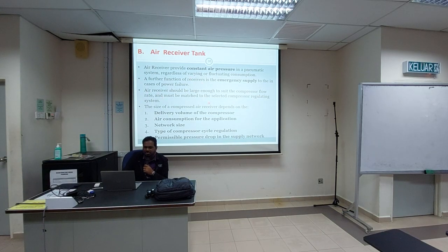Then the air receiver should be large enough to suit the compressor flow. So the air receiver tank must be enough for your application. If your application needs a lot of compressed air, then you need to use a larger tank or many tanks. You can decide whether you want to use many tanks or a bigger tank. Okay, so it's up to you, as long as you can supply your emergency supply.